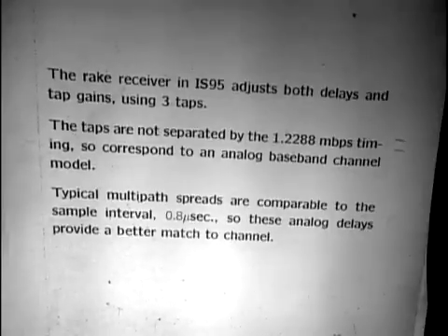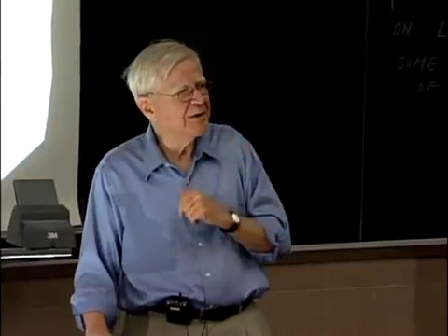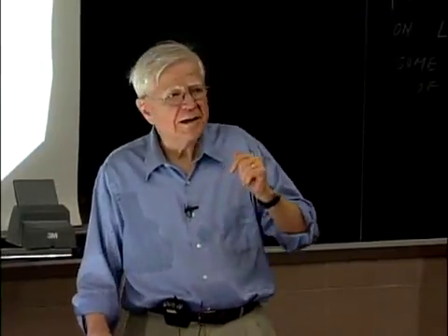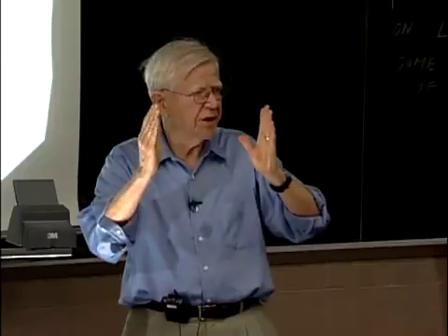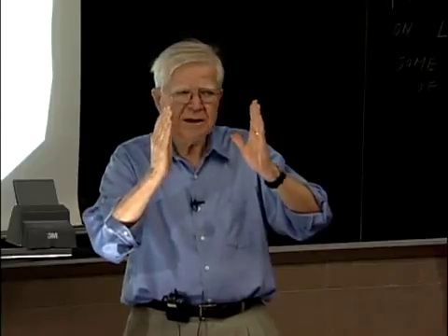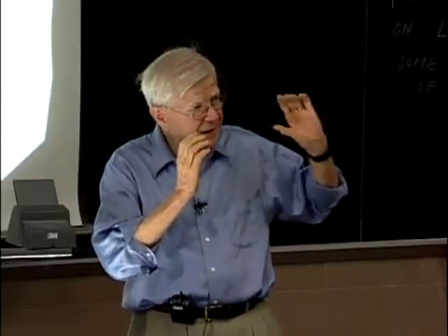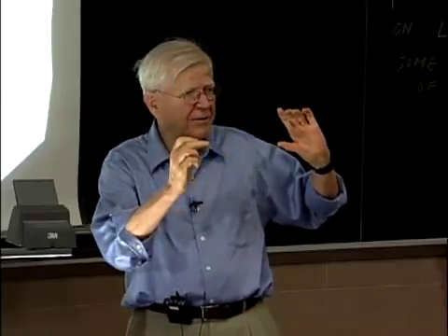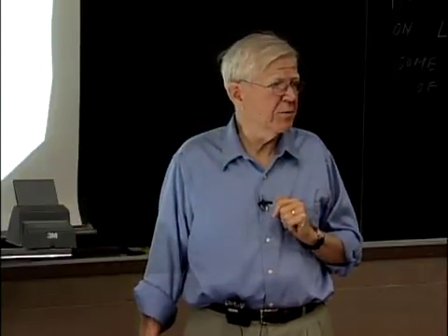I mean, we sort of showed that the digital model was completely equivalent to the analog model. But then I cheated you. I didn't realize I cheated you until about 9 o'clock this morning. But I cheated you in the following way. I told you that if you modeled the channel in terms of a discrete set of taps according to the sampling theorem, this was completely equivalent to trying to model it, as far as a band-limited input was concerned, in terms of an analog filter. And that's absolutely right if you use an infinite number of taps for the channel.